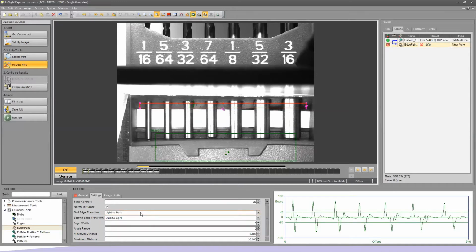If you have already watched our previous video on edges, this arrow for the point of origin tells me my tool is processing from left to right. So instead of looking for light to dark and dark to light, now I want to look dark to light, light to dark, because I only want to count the tops of the glare, since there's only one for each bit. And you'll notice now I have green edge lines on each bit. If I look under my tool palette, I'm now counting 7, which is correct.